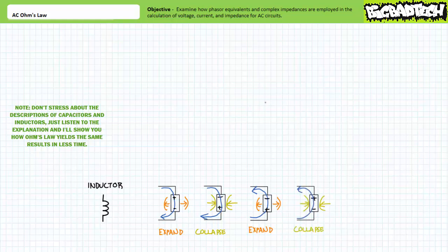Experiencing a decrease in current, the collapsing magnetic field continues to push current out of the top terminal by generating a voltage differential across the inductor, positive to negative, top to bottom. In this sense, the inductor is again acting just like an active element, supplying energy.